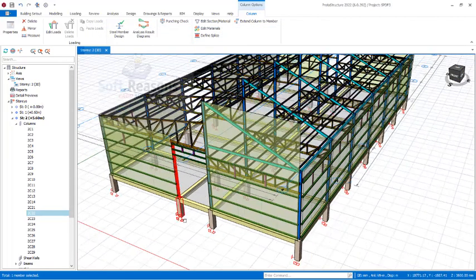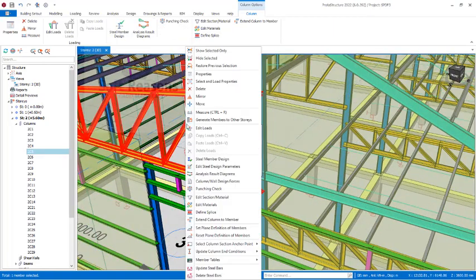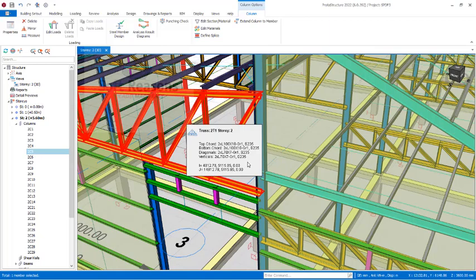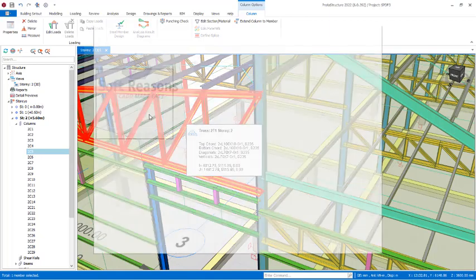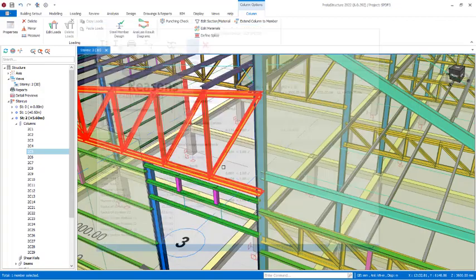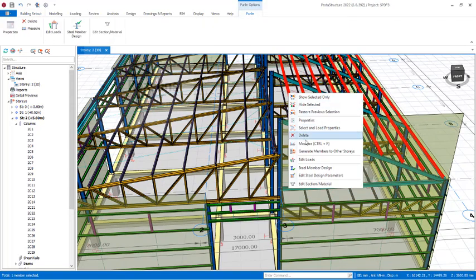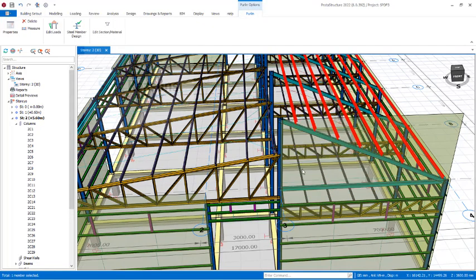The next thing, let's check the trusses. You select the trusses right there, right click, and then you click on the steel member design. For the trusses, you can also look at it. It has also passed design successfully. For this one that we applied load on, the horizontal polyline, select that, right click, and then you click on the steel member design.